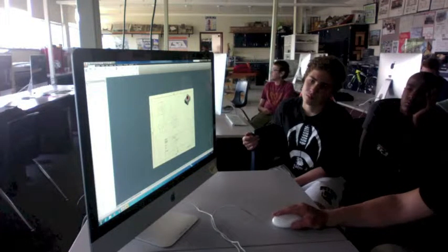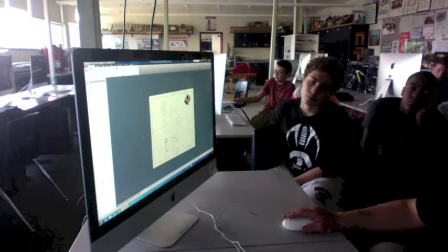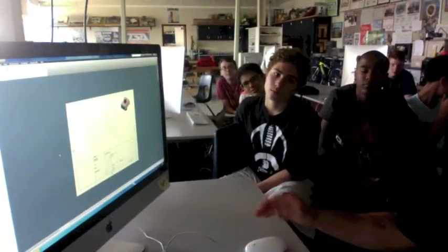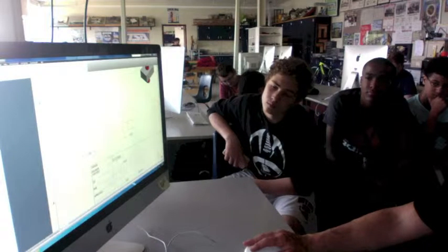Okay, so now what do you got to do? The only thing left to do is to dimension your part accordingly. And let me bring that further so you can see it. So now I'm going to annotate it with dimensions under the annotate tab. Dimension, I'm going to do my basic ones for today. My overall length. My overall depth here can be done on this view. And line it up with that front view. And I'm going to put my height on the right side view.